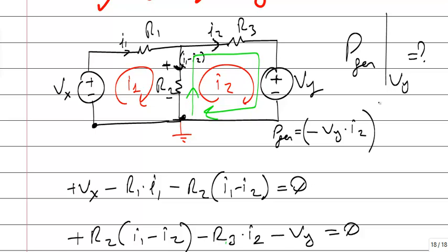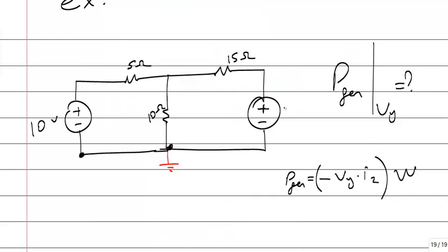This much of watts. Okay, let's analyze the circuit. Power generated by, let me say, the 20 volt source. What I should do is this: if this is the current, I should do 20 times the current, but that current is entering from the positive, so I should say a minus. There should be a minus at the beginning. Okay, 20I.